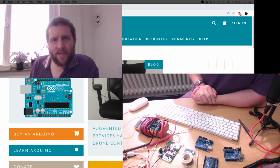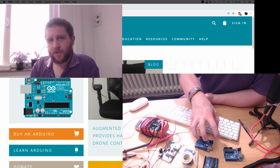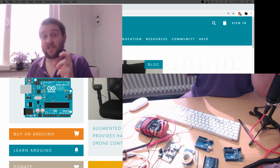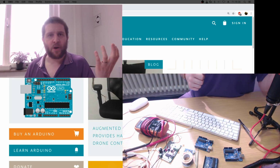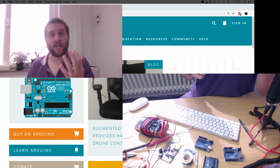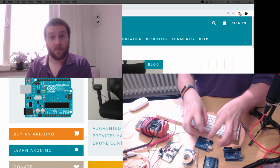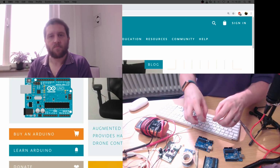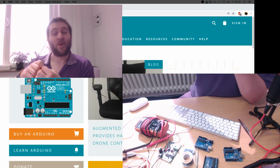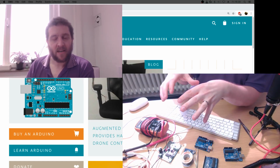Well, the way that I've come up with is to program an Arduino to just listen out for a signal or a command from Psychopy, from Python. At a certain point, Python is going to say, hey, Arduino, turn the lights on. The Arduino is really good as a microcontroller at saying, okay, I'll turn this pin on, and so this pin will be activated. When I activate that pin, it will be connected to my LED lights.